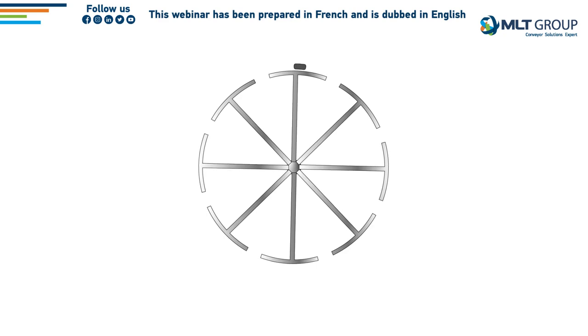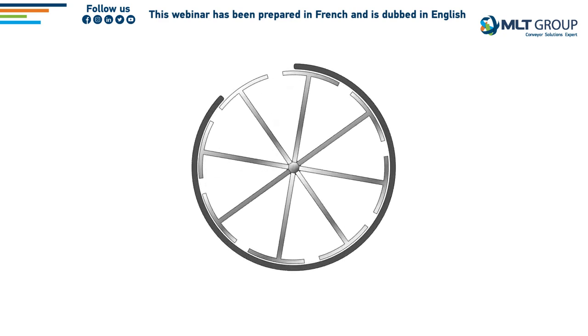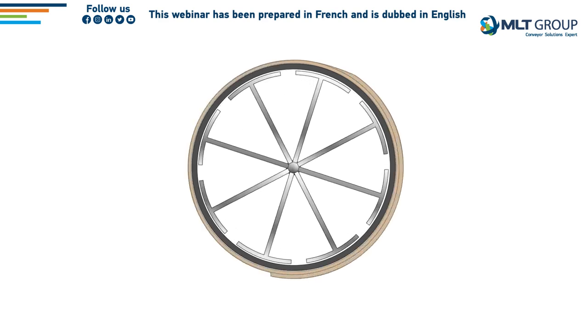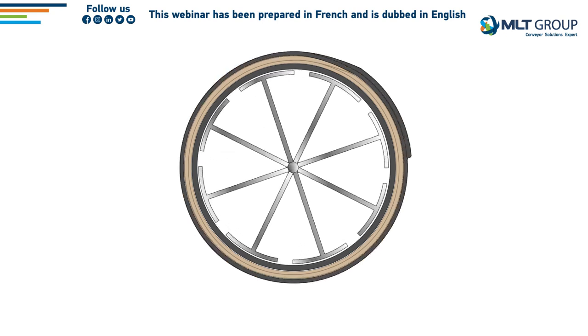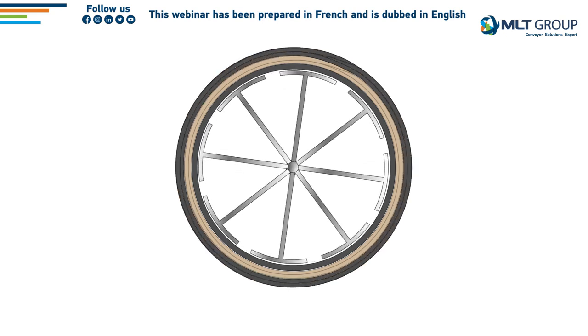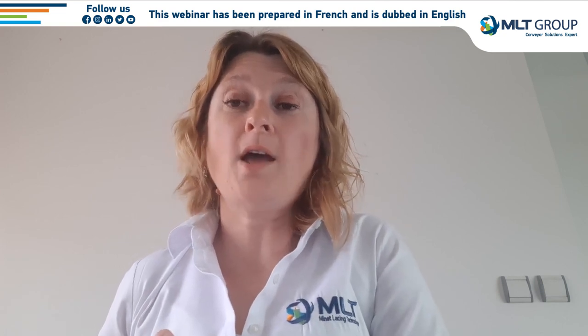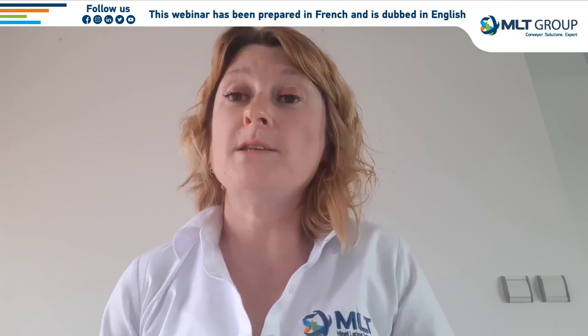Yes, of course. First, we roll the raw rubber on the bottom side. Then, continuous fabric on several turns. The number of turns depends on the desired resistance. At last, the raw rubber on the top side. As the belts are spliceless, there is no risk of belt opening. Manufactured under tension, our belts will not elongate once operating on the conveyors, so they have a better carcass, more resistant than spliced belts, and they are also more abrasion resistant, thanks to our specific rubber compounds.